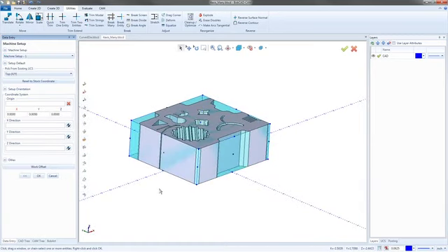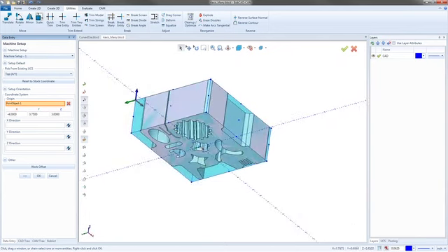Now, when you choose your origin on this part, you should be picking wherever you're going to zero out from. A lot of people go off the table, so it'll be down at the floor level, at the bottom here. So they might pick a corner like down here. Or if you touch off the top of the part, just pick your normal touch-off point. Wherever you'd normally touch off, if it's dead center, pick dead center on the stock. You might have to pick the bottom point as well.